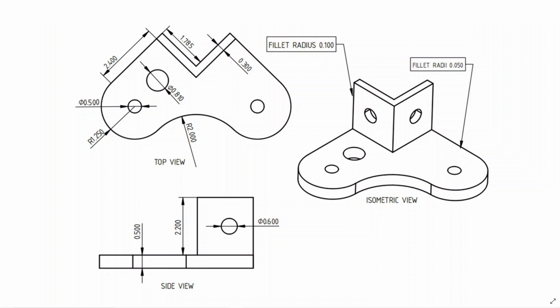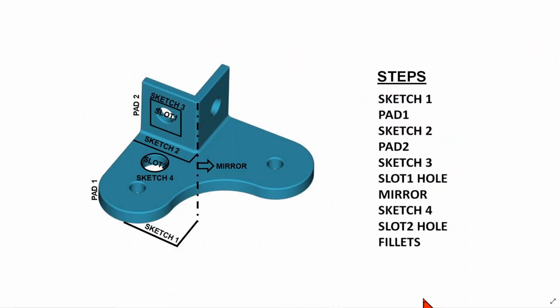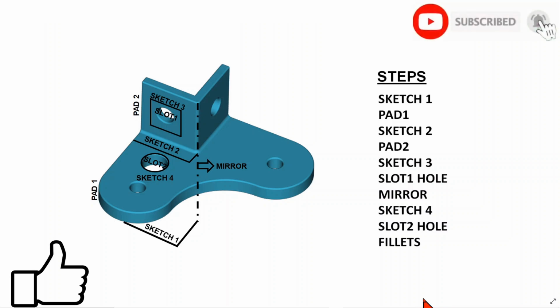So this is the tech drawing of the model. If you are given this drawing, how to model this? Based on the questionnaire we went through earlier, our model building plan is shown here. You start with the master sketch and then pad it. Place the second sketch on this face here and pad it to build the L bracket.